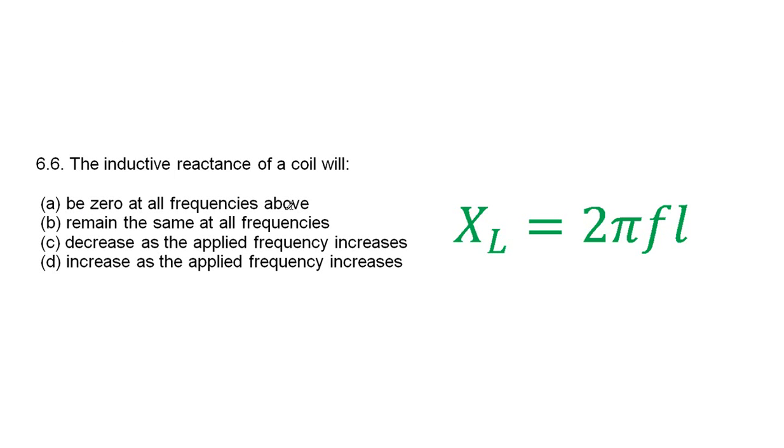Be zero at all frequencies, that's not true. Remain the same at all frequencies, that's not true. If it remained the same at all frequencies, F wouldn't even be in the equation. Decrease as the applied frequency increases? No, it's a direct proportion. If F increases, XL would increase. The inductive reactance would increase as the frequency increases. Inductive reactance is directly proportional to F and L.